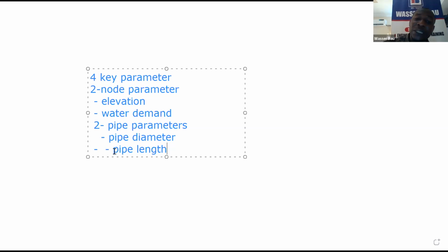It helps you to design the pump so that the pump is not just to take care of the geodetic difference, the height difference, but also to push the water through the pipes. Of course, there will be resistance, there will be changes, and you have to push it in such a way that it will not lead to supercritical flow. It will push it within a certain velocity, which we discussed last week.